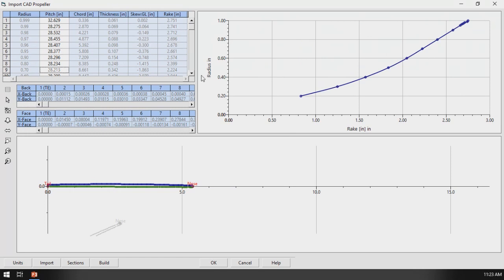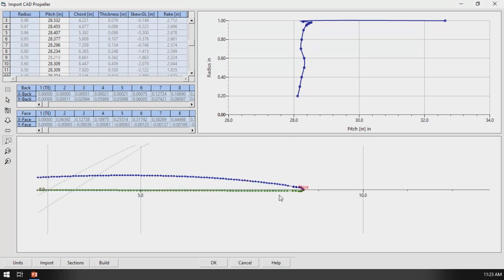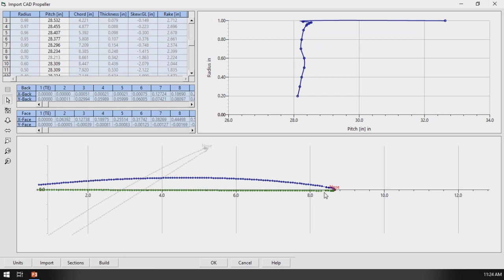So one thing we had mentioned earlier was setting pitch planes. So you can see down here, we have our section shape. We can zoom in and take a look. Now, I would actually probably want this nose point or the pitch plane to be based off of a face-based pitch plane instead of a nose tail. So if I wanted to change the pitch plane, I can grab a point, say right here. I can click that point and I can just say set this as my nose point. It shifts it up. And what you'll also see is that the pitch for this section changed just slightly.